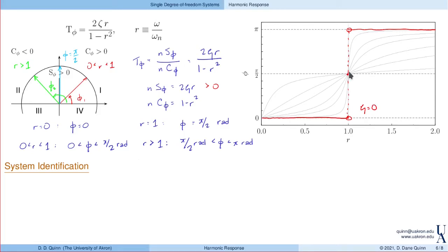As we increase the damping, it smooths this curve out. So positive damping, but small, gives us a plot like this. And again, continuing to increase the damping gives us the following. Let's just keep drawing these curves. And we'll notice something interesting in just a second. Here, these values correspond to the values that we chose for the magnification factor.